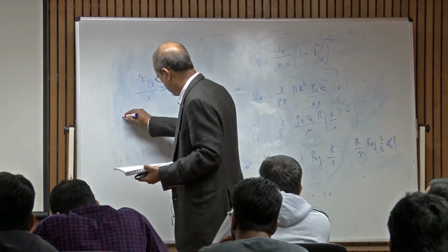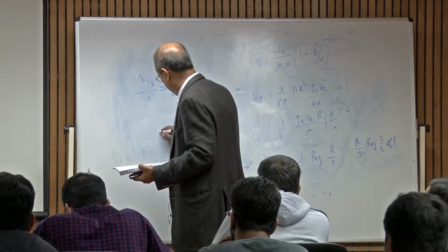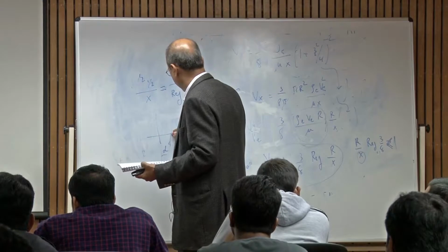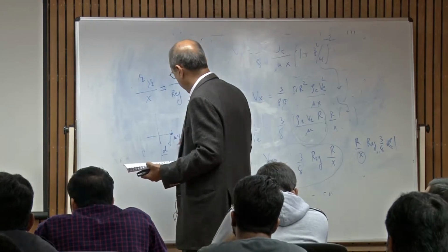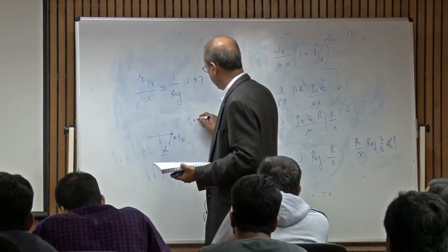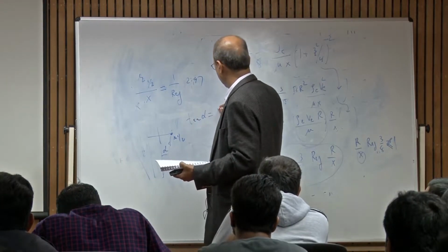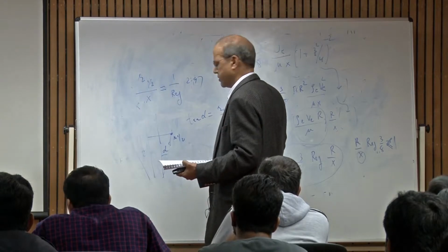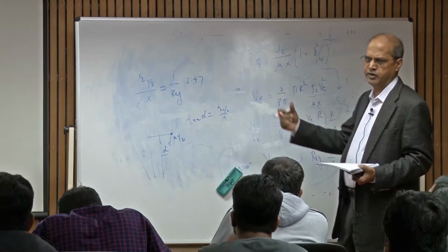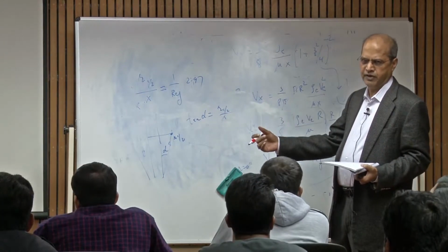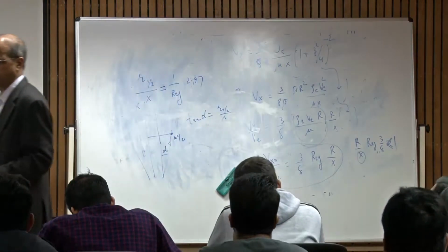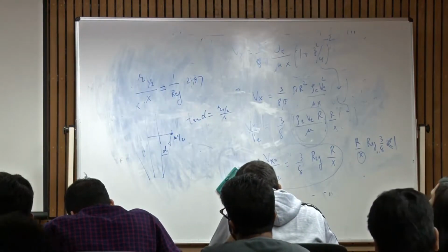So, this spreading angle, because this is r 1/2 and this is x. So, spreading angle is simply tan alpha, which is r 1/2 over x. Okay, so, that gives, based on that, the velocity drops to 50% of the center line value. You can also define using YF becomes half of center line value.